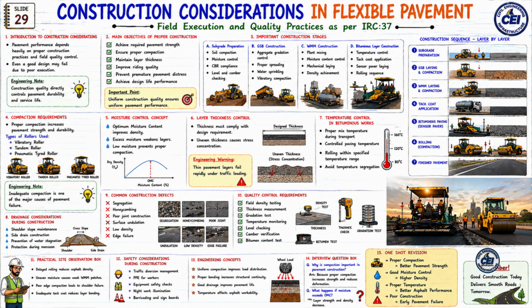Now let us look at the 12th topic. 1.2 Safety considerations during construction. Construction zone safety is also equally important. Traffic diversion management. PPE for workers. Equipment safety checks. Night work illumination. Barricading and signboards. And improper safety management increases accident risk.